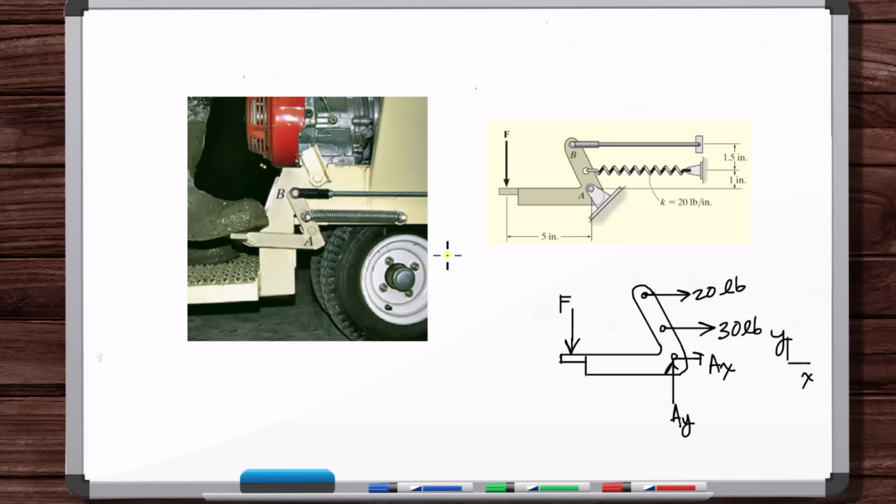Do you know for sure if that contact is really no force there? But if you're not sure, then you'll have to put it as an unknown force. But also analyze it to see, do you at least know the direction of the force from that contact? So maybe it's an unknown magnitude, but you know the direction of that contact. And so, just to give you an idea, if there's smooth contact, meaning the frictional forces are negligible between the two surfaces, well, then the contact force is going to be normal to the surfaces.